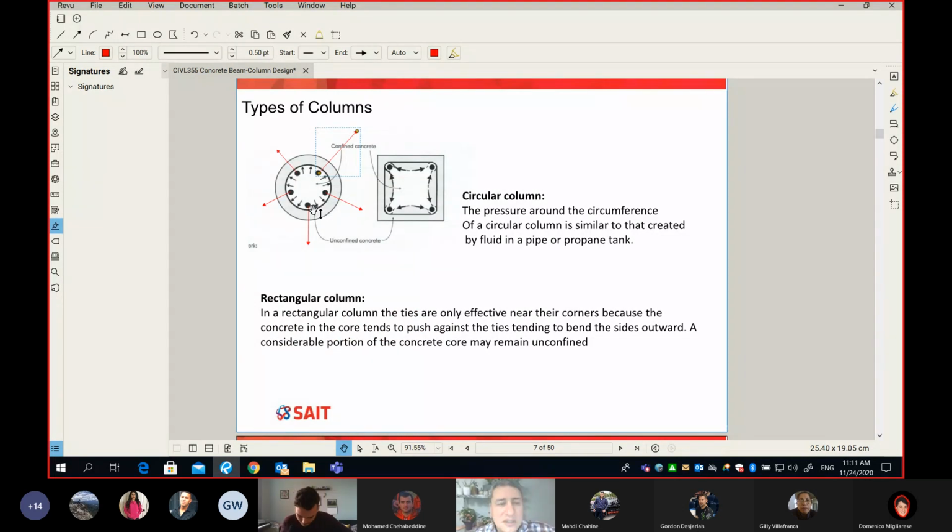That's exactly what's happening. Same as if you have a container that's full of hydrostatic pressure, then the membrane of the circular container will have a tension. That's correct. But remember, this applies mainly for circular columns. Now, when you think about a square or rectangular column, it will be different. If we have bars in a square column, we have bars on the corner only. See what happens? Those bars are trying to go to the outside, same, no change. And this will cause tension on our tie.